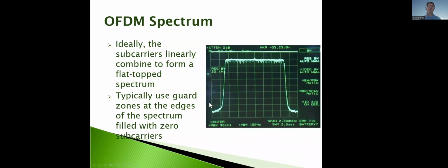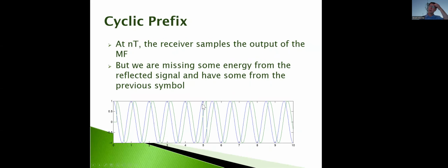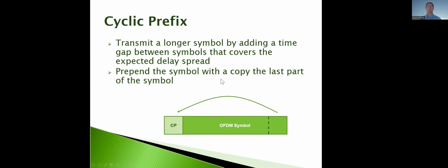But yeah, hopefully you can understand that concept, and that's what I'd look for, is that there is this discontinuity. That's okay, except that it's offset in time. And so we're going to take a copy from this end of the frame and stick it up here, or into this symbol. Sorry, frame's not a good choice of words here. Into this OFDM symbol and paste it up front here so that we smooth this out.